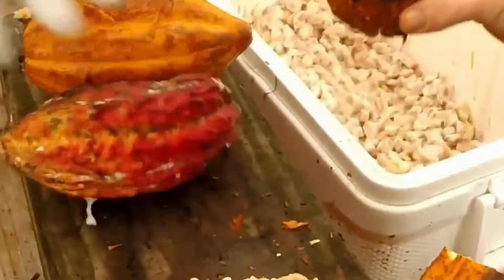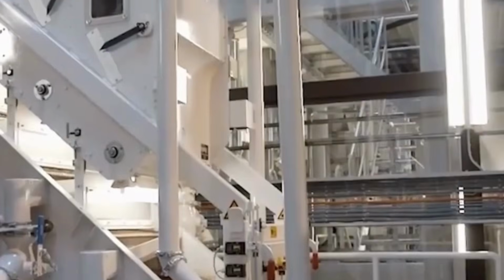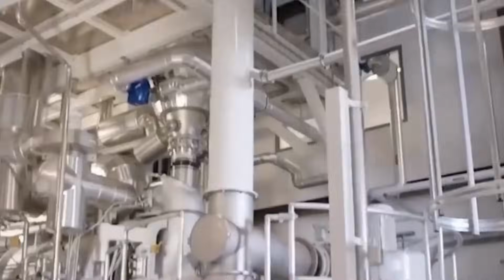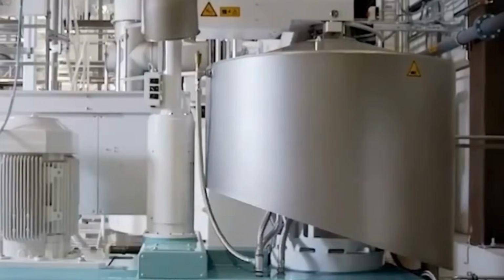Routine inline quality control includes sampling from every production hour. Samples are weighed, measured, and evaluated for coating thickness, layer adhesion, caramel placement, and hardness using calibrated micrometers and texture analyzers. Moisture content is verified using halogen moisture balancers, and chocolate temper is tested with temper meters to confirm crystallization profiles.